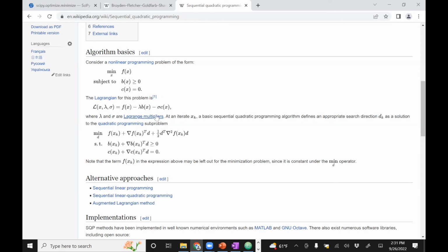So this is how it is cast. This is actually exactly how the equations of motion are derived. When we're trying to solve for the equations, we are minimizing the Lagrangian subject to the condition that those constraints are met. That is, the forces keep those points, whichever the robot makes in contact, stationary.